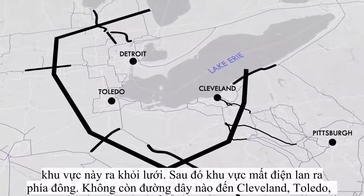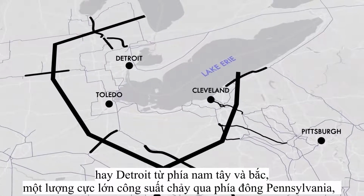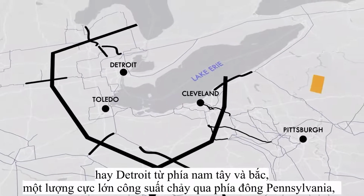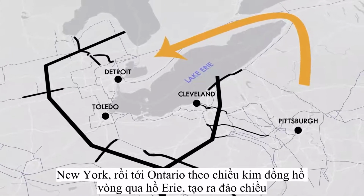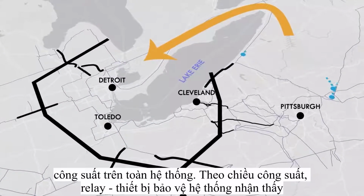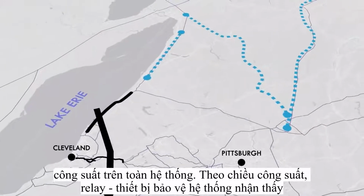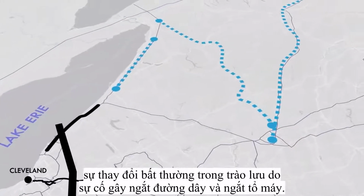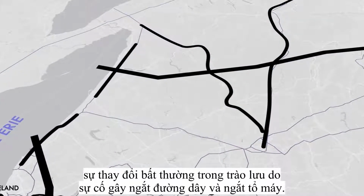With no way to reach Cleveland, Toledo, or Detroit from the southwest or north, a massive power surge flowed east into Pennsylvania, New York, and then Ontario in a counterclockwise path around Lake Erie, creating a major reversal of power flow in the grid. All along the way, relays meant to protect equipment from damage saw these unusual changes in power flows as faults and tripped transmission lines and generators offline.